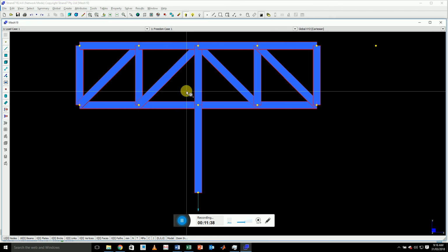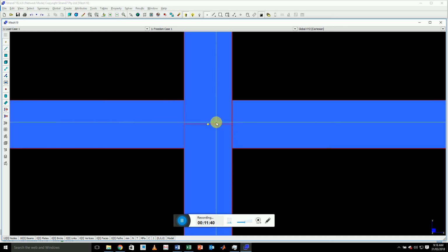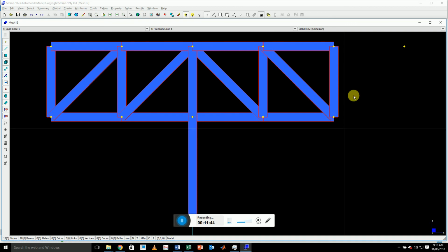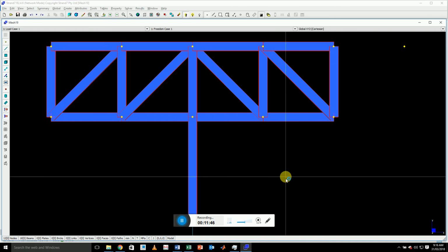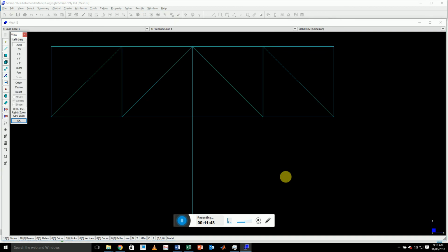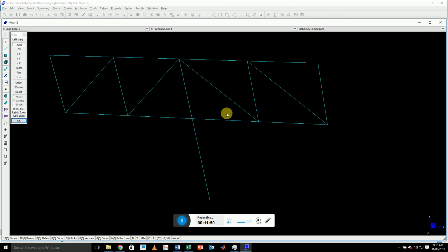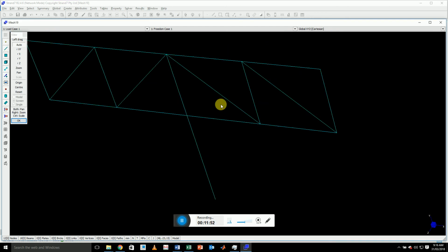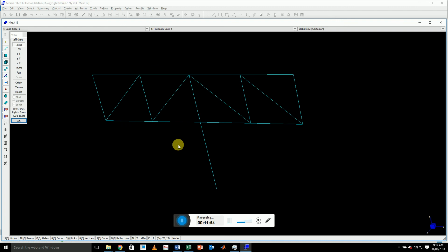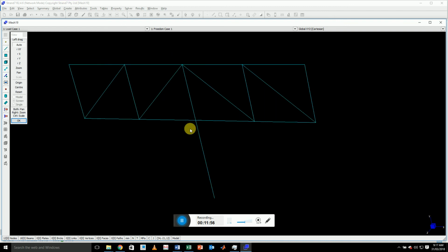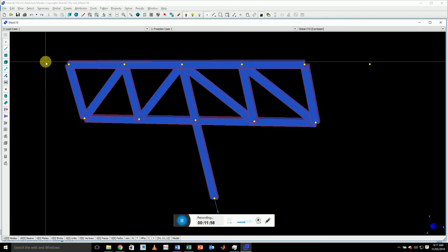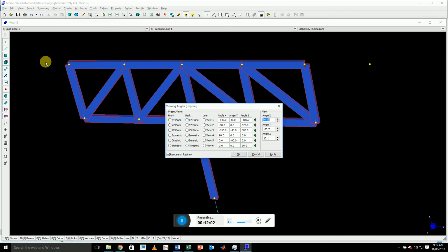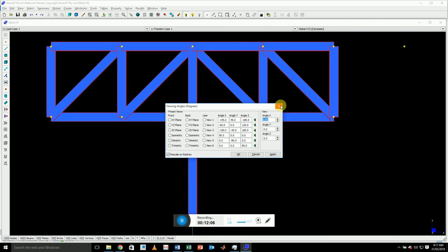F6 is to zoom in. You just draw a box to zoom. F3 puts everything in your universe centered in the middle of your screen. F4 for rotations, and then that's a left click to rotate and a right click and move your mouse to zoom. It's weird, it's not nice, but you get used to it pretty quickly. F12 brings your view window up and you can go back to X12 plane. They're the ones I use the most.